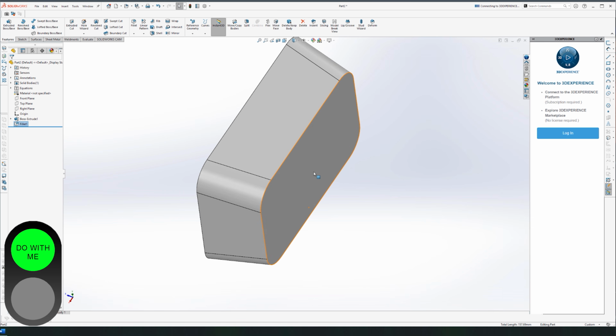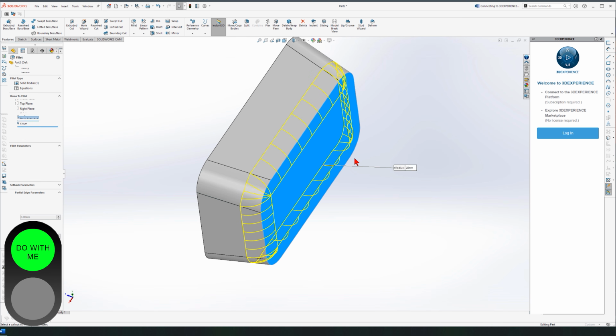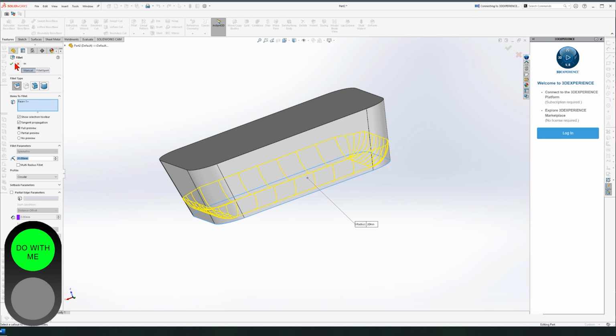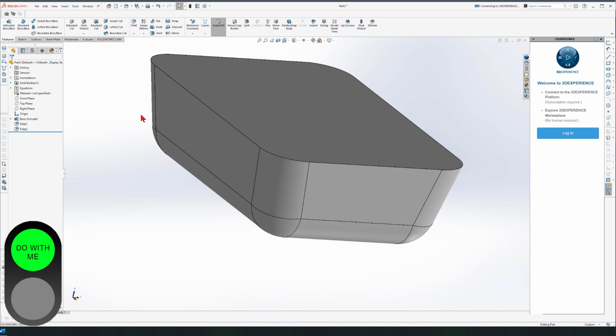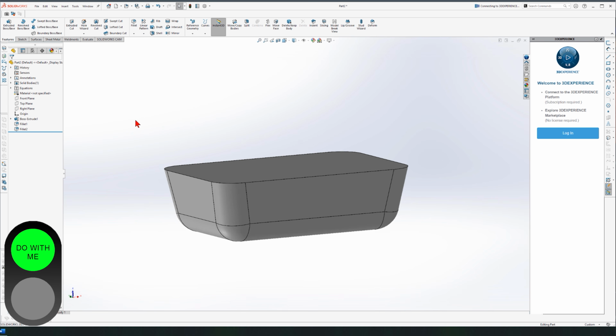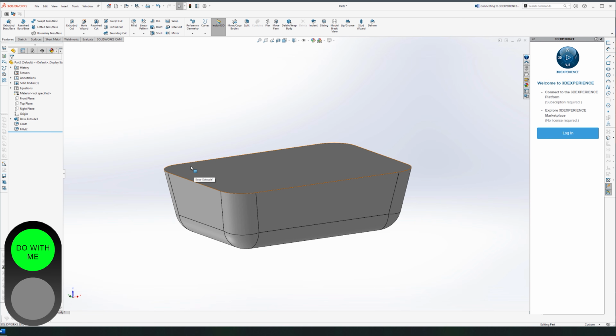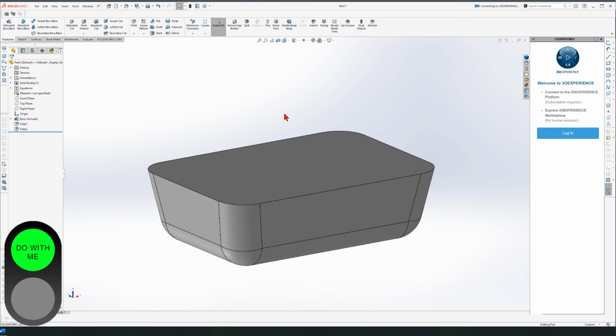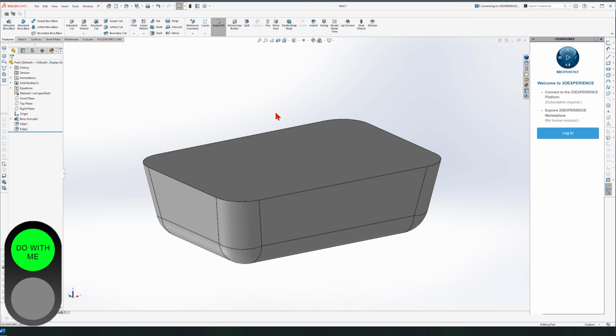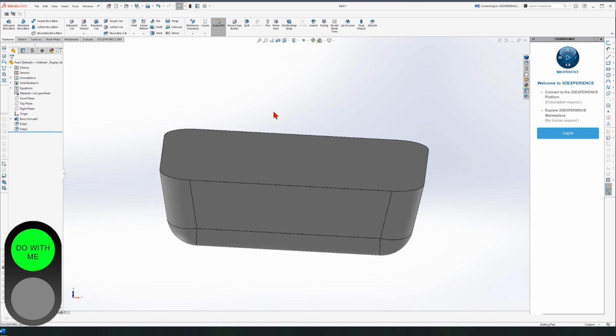Now, this back, also fillet, radius 20. So far, so good? Good. But we need to have our item hollow, right? And the wall thickness is about 1 millimeter. How do we do this? What's the best way to do this?